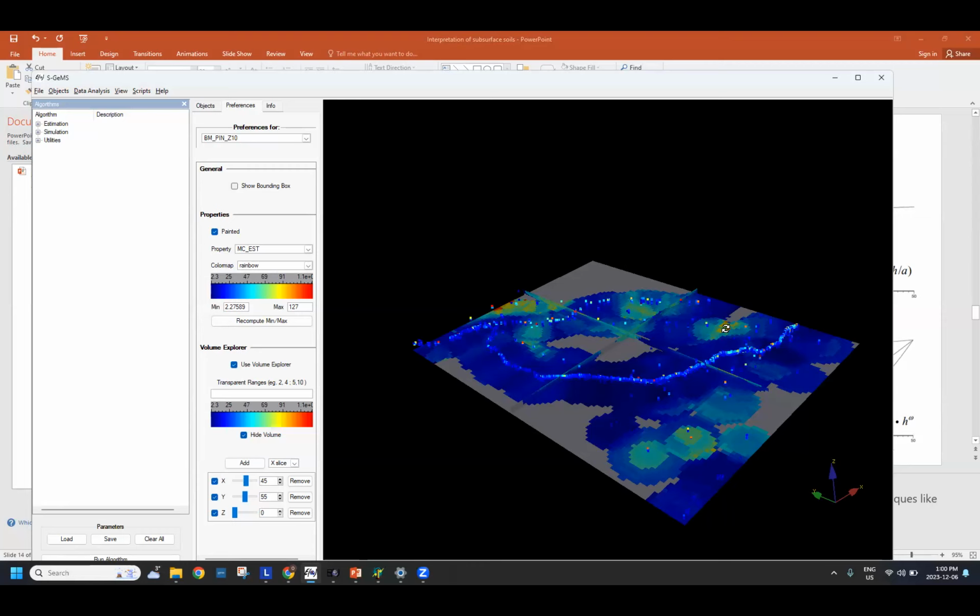We change different variogram parameters, the number of samples taken from one borehole, the octant and the radius of the search ellipse, and then according to the cross-validation method, we choose the best one. Finally, we can validate the results by visual validation.